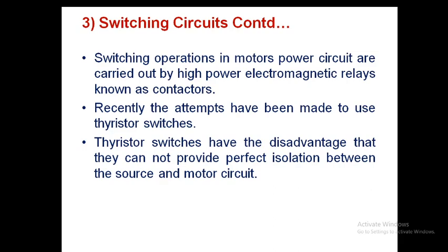For that we again need an isolation circuit, which again involves cost. Otherwise the thyristor switch is a good switch and gives better performance, but because of the isolation problem, it has some restrictions.